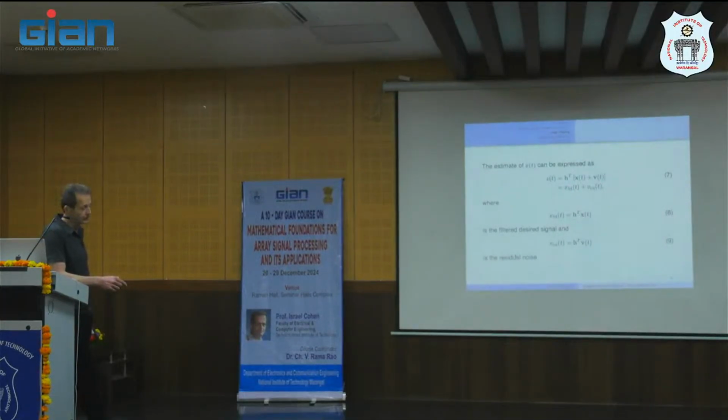This is the advantage, that we can define things more easily. This sample contains two components. One component is the filter desired component, and the other is the residual noise, which is H transpose V. Ideally, we want the filter desired to equal the original clean signal.